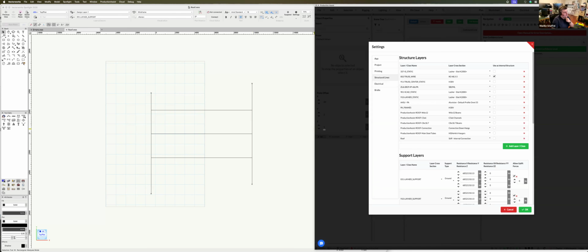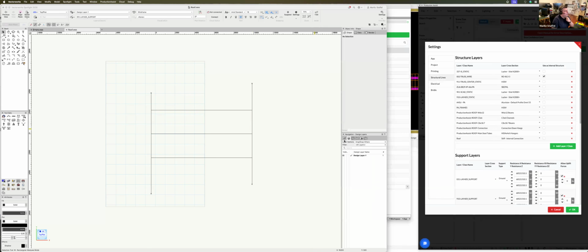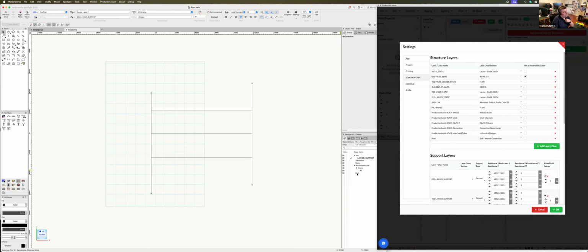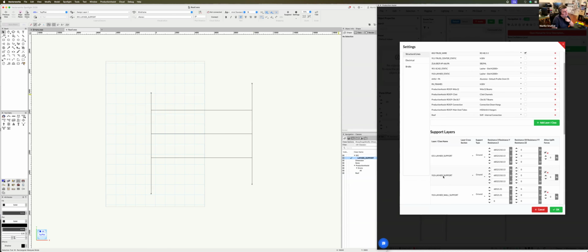If you look into what I'm showing here, you see that I already created everything. So you have a roof class and a layer support class. The roof class is mapped to the internal connection thing here so that it's not generating a workload by default. And I have added some points on the layer support class, which will be used as the supporting points for the roof.